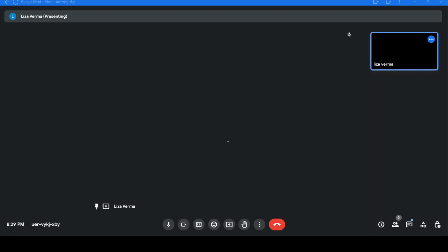First return instruction may appear before the first call instruction. If you have return at 0000, that just resets the MUP, right? That's the vector location for RST 0. So the 8 bytes from 0 to 7 are reserved for RST 0.